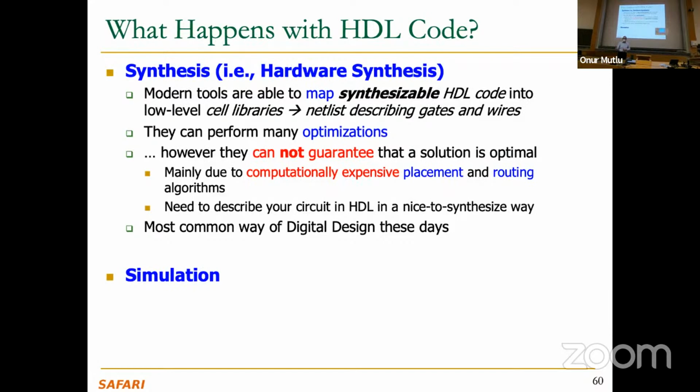So there's a portion of digital design, which is a very large portion that's today automated. But there's some portion that's really important, smaller portion, that's essentially either semi-custom or full custom. You may actually hear the semi-custom and full custom terms. What does this mean? Basically, you go and change things by hand, or by looking at it and actually changing the gates this way. Oh, I want to implement this gate as opposed to this gate, even though the tool implemented some other gates. Right? So there are portions of the design today where you have to do this because the tools are not good enough. Okay, but you're going to do that in the lab somewhat to learn. So that's a good way of learning.